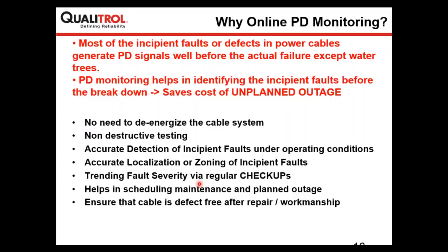And when you do online partial discharge measurement, there is no need to de-energize the cable system. It is non-destructive testing. We will not be overstressing the power cable. We will not be applying any external voltage. The cable will be operating under normal conditions. And if we apply the technology in the correct way, by which I mean if we know the cable grounding scheme, then we can accurately detect and locate, or in the second case zone, partial discharge along the length of the power cable.